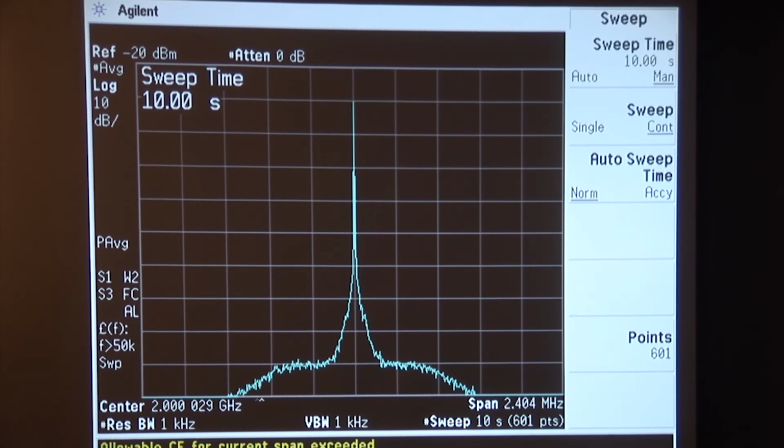It is sort of the last piece of the puzzle in terms of getting a good convolution measurement on a spectrum analyzer, and that is just bear in mind that you want to make sure that you're not spanning too much spectrum in comparison to the width of your IF filter and the number of points that you're sampling. One very, very last thing that we can do with a spectrum analyzer like this is we can keep on sampling the same amount of spectrum, but we can, with this analyzer, boost the number of points that we're measuring with. Instead of 601 points, let's go to 2,404 points.